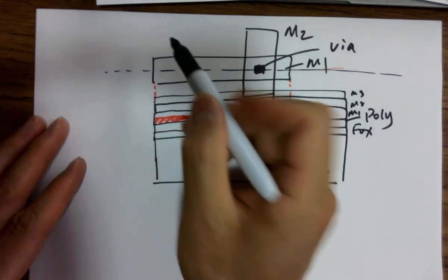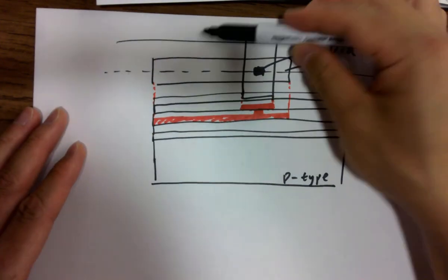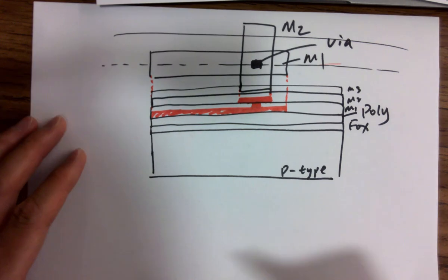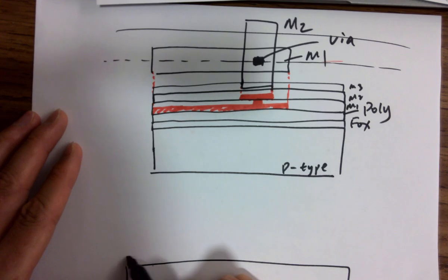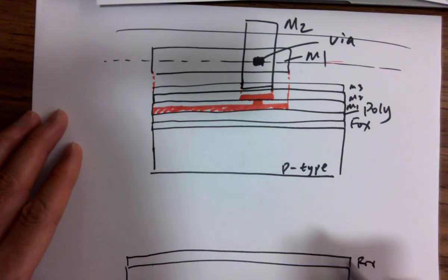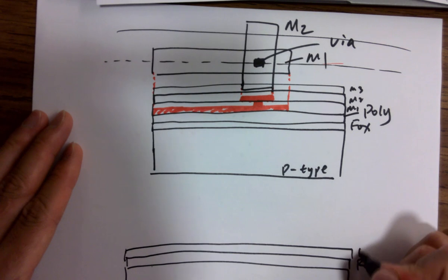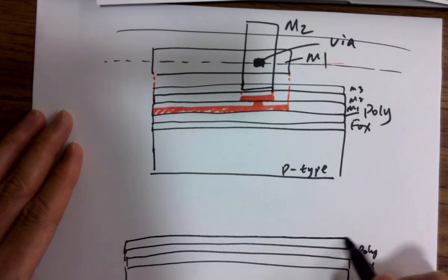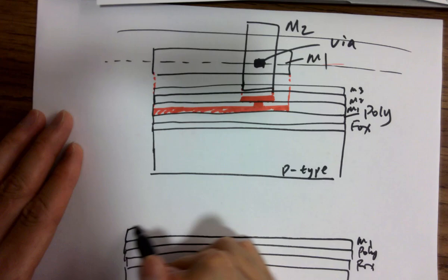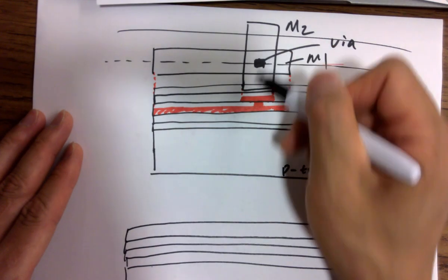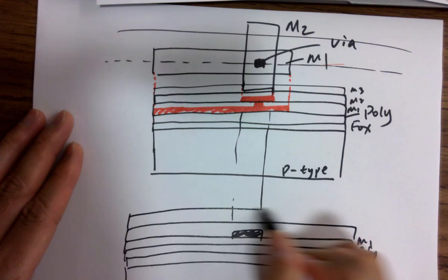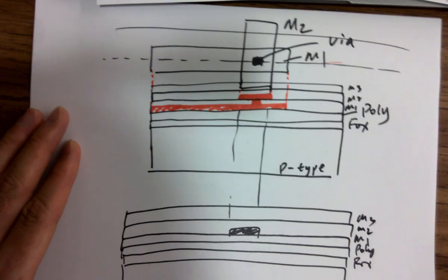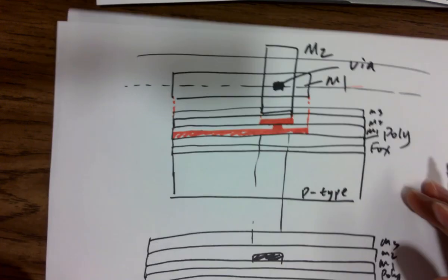So what if I draw a line here, like here, metal 2, to make a cross section? Yeah, cross section. I guess draw the layers. Fox still stays, right? Yeah. Poly stays, but nothing. Metal 1 stays, nothing. And metal 2 has something, which is this piece. You've got a metal 2 here. Metal 3, nothing. Make sense? Cool.